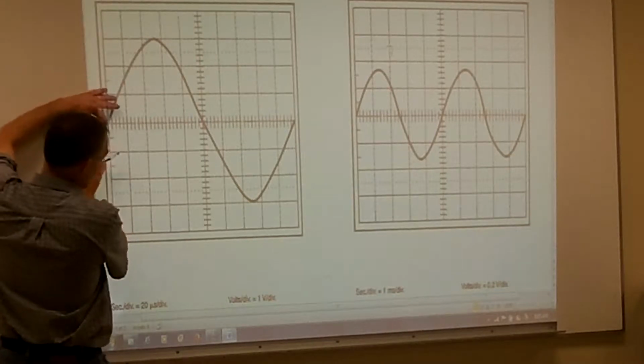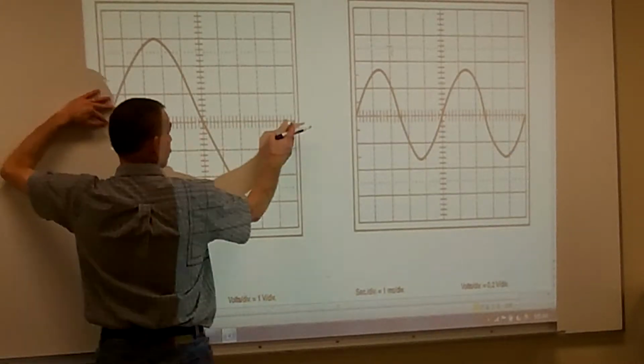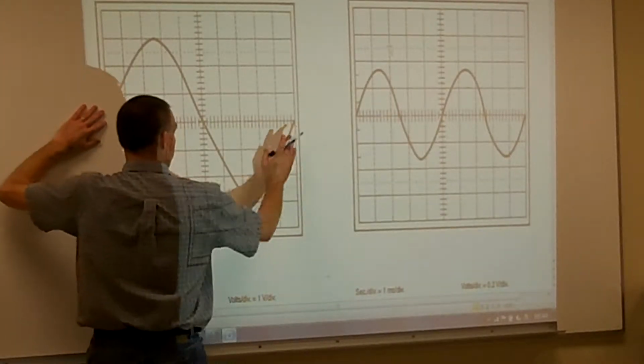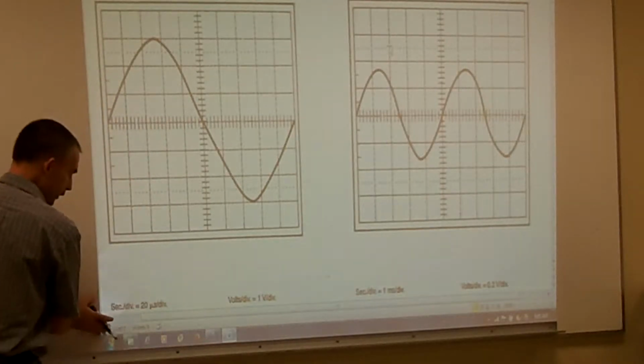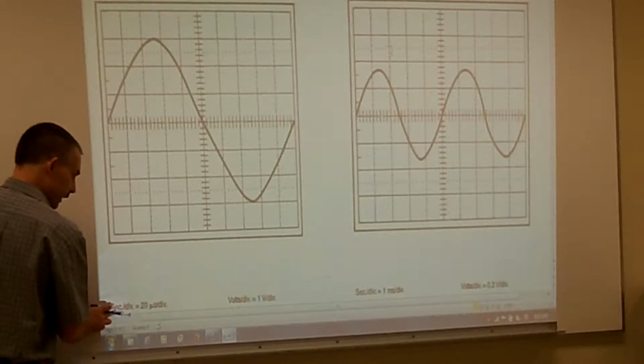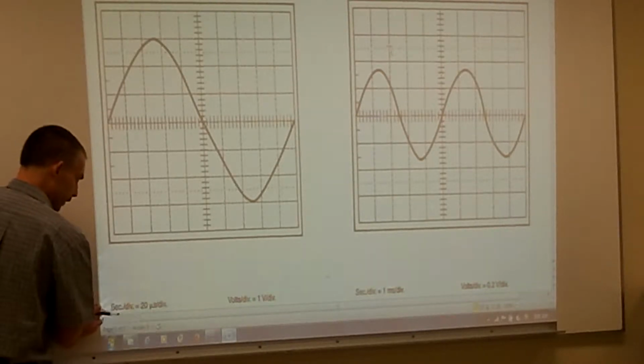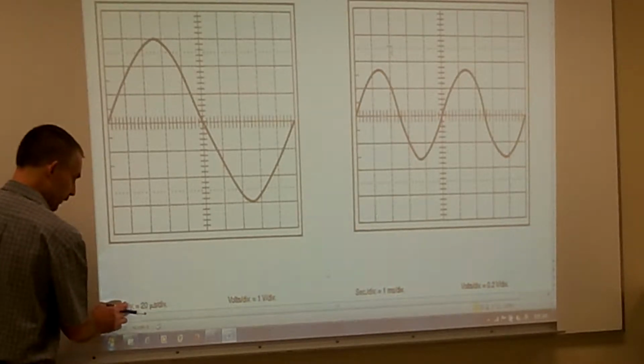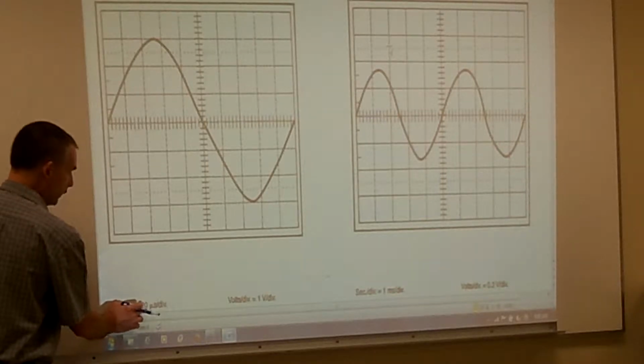We'll take a look at what our period is across here. On the bottom of your screen, on your oscilloscope, it's going to tell you what your setting is set at for your horizontal divisions. And it's going to say how many seconds per division. So for this particular one, it's going to be...